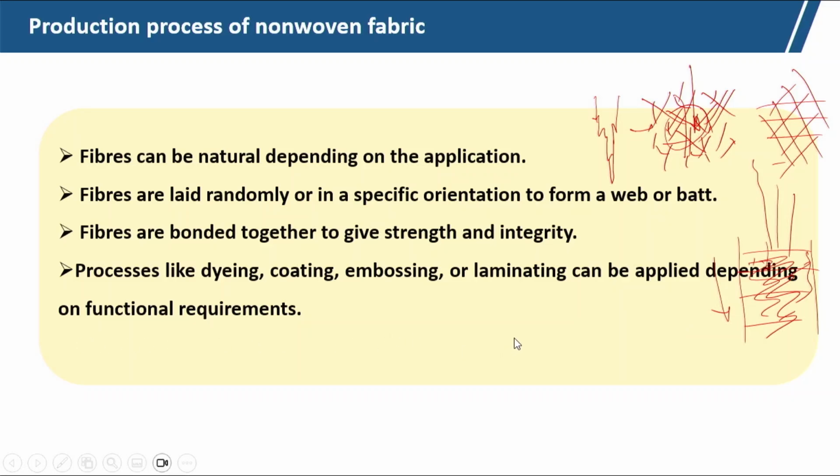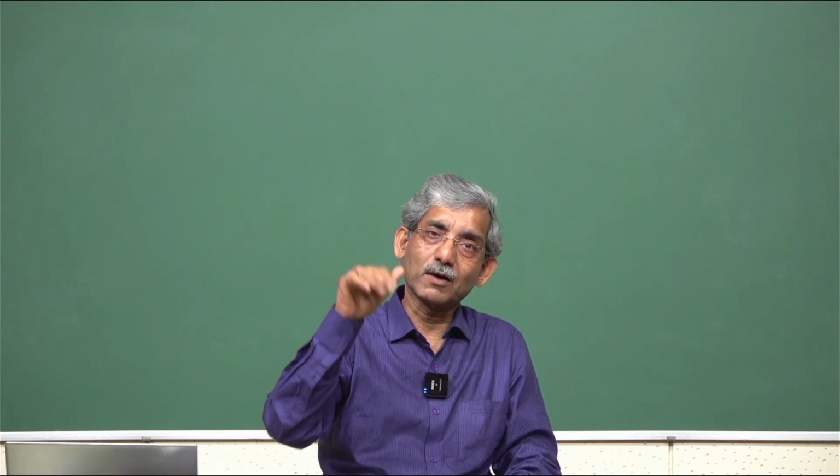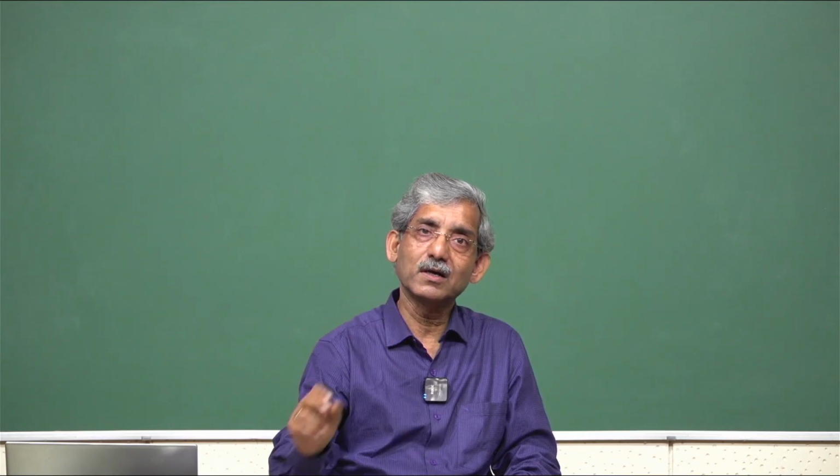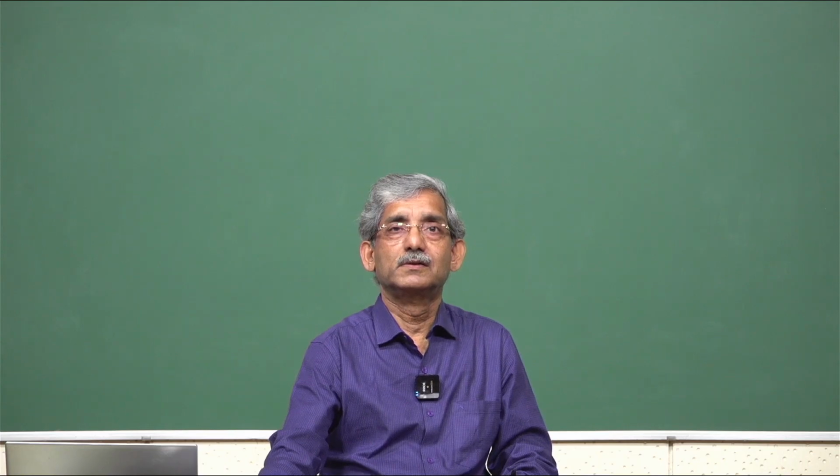So, if we want waterproof, breathable, we use some laminating film which will provide the waterproofing characteristics along with the breathable nature. The characteristics of nonwoven fabrics: it is lightweight and soft because of the web structure. Directly, no yarn is formed, it is lightweight and soft.